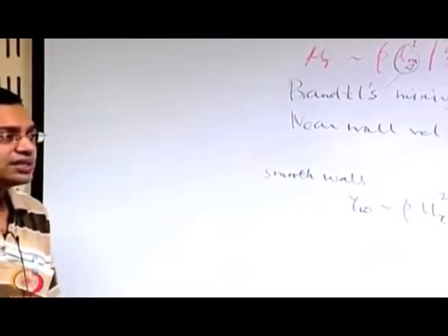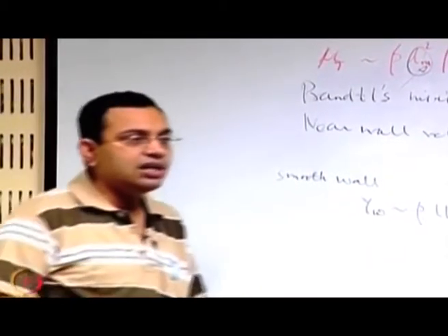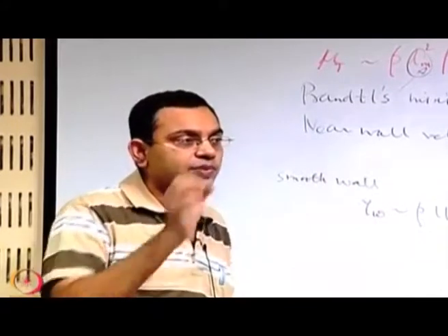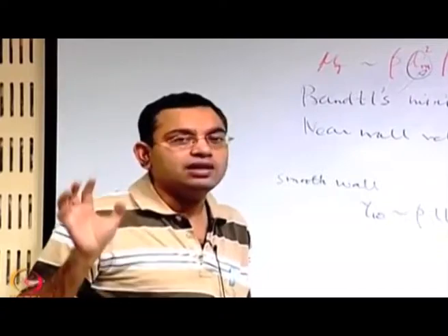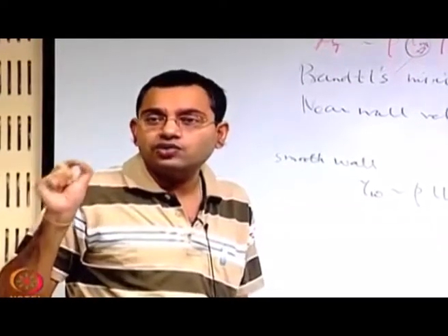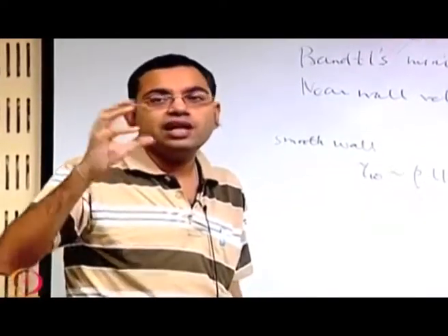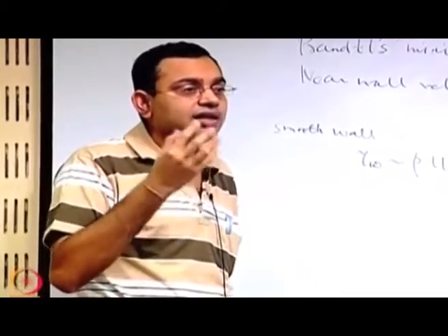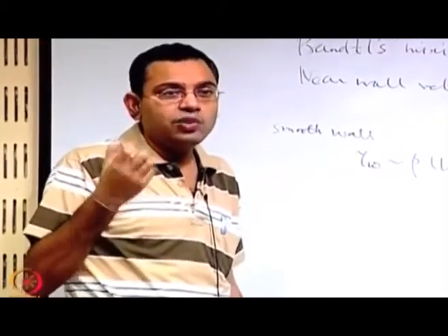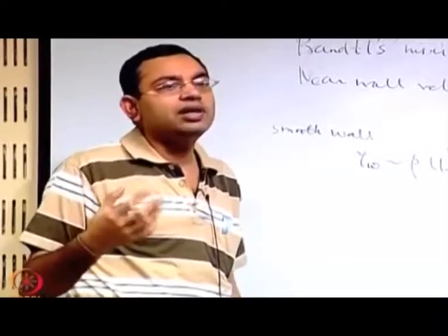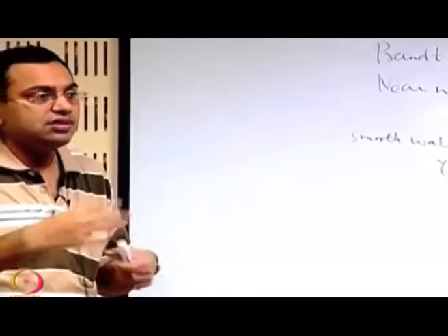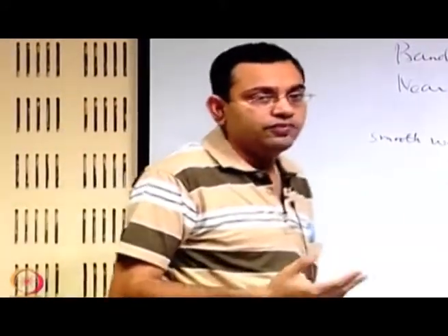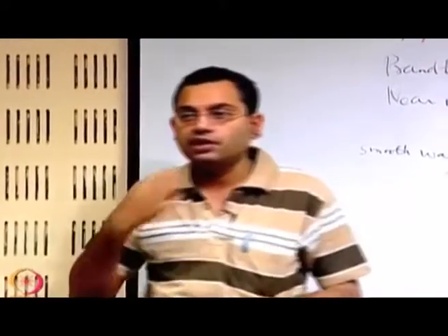We have also discussed earlier that large eddies have a lot of anisotropy, but small eddies have virtual isotropy. Small eddies are not perfectly isotropic, but they have greater isotropy than the large eddies. Not only that, small eddies have certain important characteristics: sometimes they appear in patches and disappear. These are known as intermittency in turbulent flows, and very involved concepts are related to this.